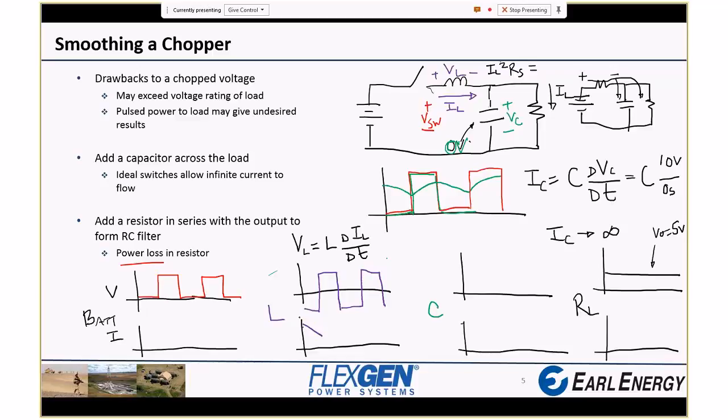So inductor current is changing at a constant negative rate while the switch is off. When the switch turns on, the voltage across the inductor changes instantaneously from -5 to +5. Now the current is increasing, at the same rate that it was decreasing before.